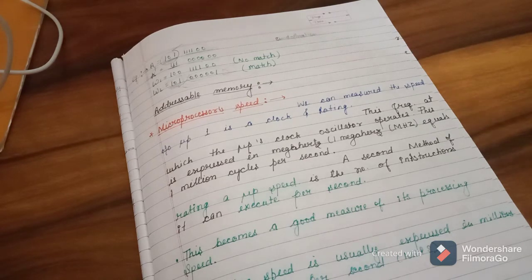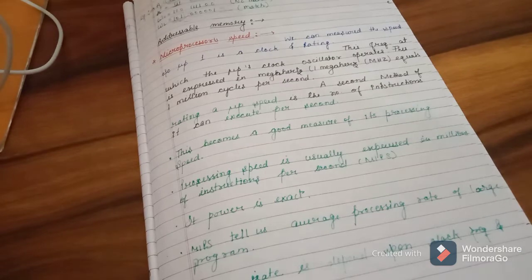The first is the frequency at which the microprocessor clock oscillator operates, expressed in megahertz. 1 megahertz equals 1 million cycles per second. A second method of rating microprocessor speed is the number of instructions it can execute per second. This is a good measure of its processing speed, usually expressed in millions of instructions per second, or MIPS. MIPS tells us the